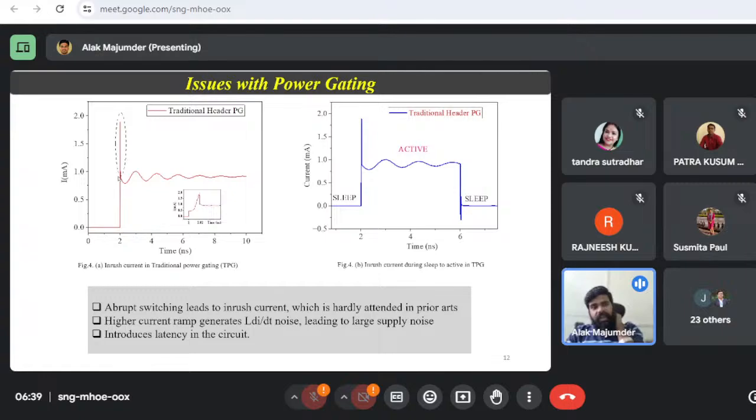And this doubling matters. For example, you have purchased a device where the specification is 10 milliampere, and instantaneously it is hitting 20 milliampere, your device will burn out. Your device will never sustain. And also think of the DIDT at that instantaneous time. DIDT means change in I divided by change in time. Change in time is very small. Change in I is huge.